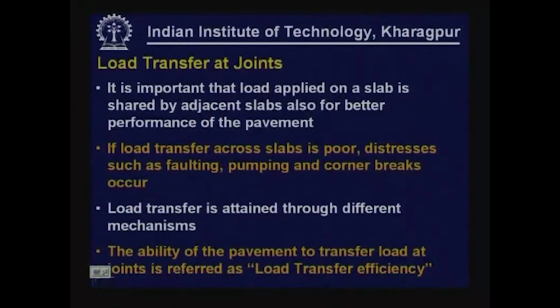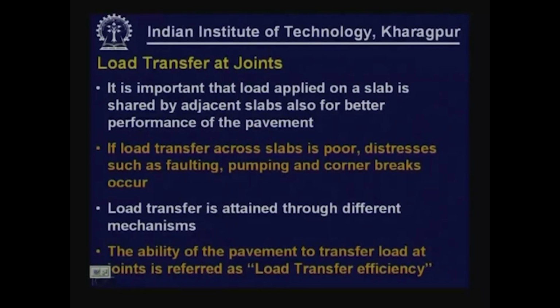It is very important that load applied on one slab is shared by the adjacent slab for better performance of the pavement, to reduce the overall deflections, and to reduce the stresses in the slab and also on the foundation. If load transfer across slabs is poor, distresses such as faulting, pumping, corner breaks and various other problems occur.